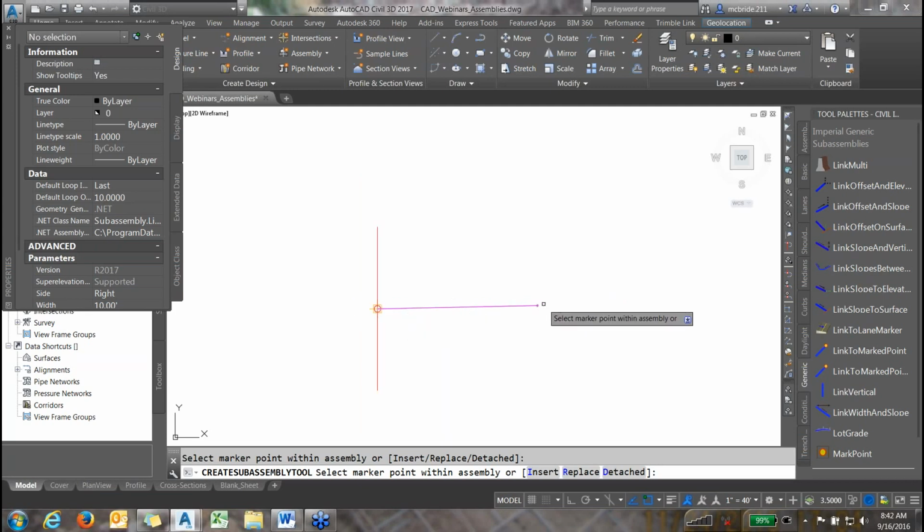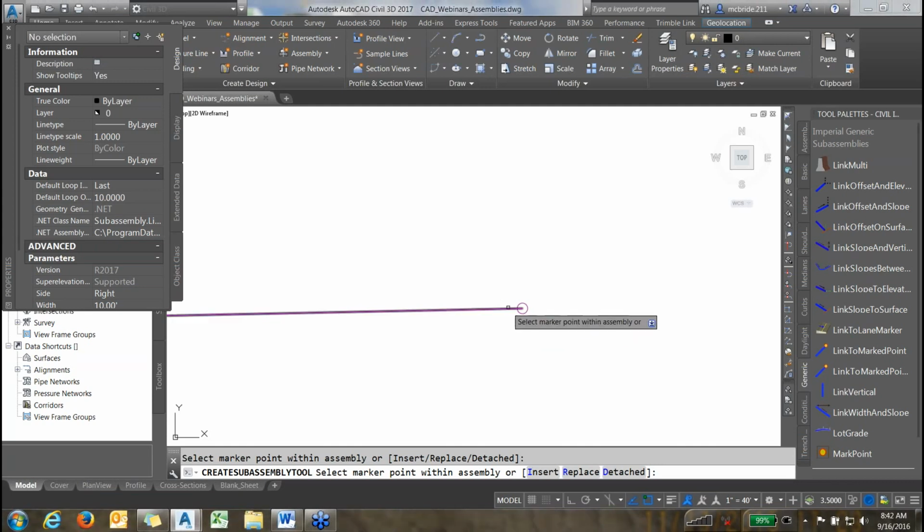So this is the first one I want to do, but for a parabolic waterway I need two more, and I'll explain that once it's done. But for parabolic, you always want to have three on the right for these first ones, and then one on the very end. So I'll explain it once it's all done, but basically I want to do this two more times. So I come to the far right of this subassembly that I just created and select the circle.